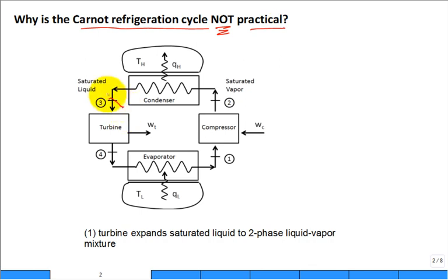Because a turbine that takes in saturated liquid at high pressure, that's good, it's high pressure, puts it out at low pressure, but think about the temperature. It's now really cold. And think about the quality. Maybe it's 20%, 30% quality. It's kind of a liquid vapor mixture. You brought in liquid. This thing doesn't work. We can't buy one of those. Go try and buy one. You can't. So this thing doesn't work. This turbine is hard to manufacture and hard to bring in production.